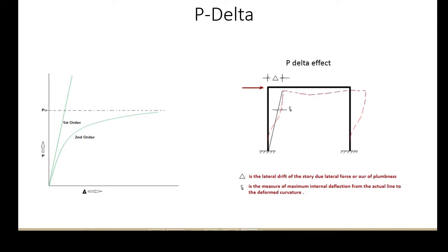And the second one is the stiffness modification method or the geometric stiffness method. In this method, the load-dependent geometric stiffness matrix, kg, is determined initially and the resultant stiffness is recalculated, which is the net value of the actual and the geometric stiffness. Now, with the resultant stiffness, the structure is resolved to capture the P-delta effect. Now, both the approaches can easily be simulated.